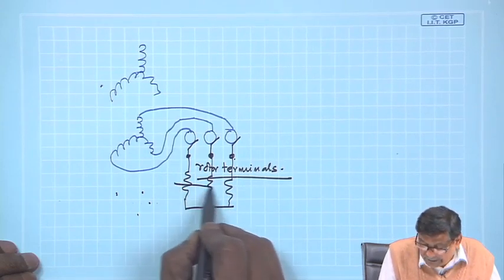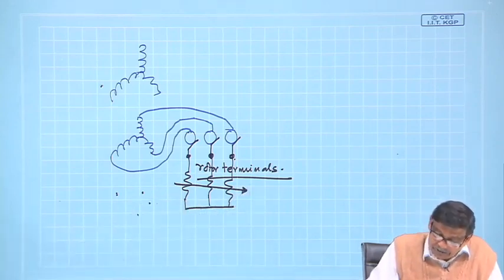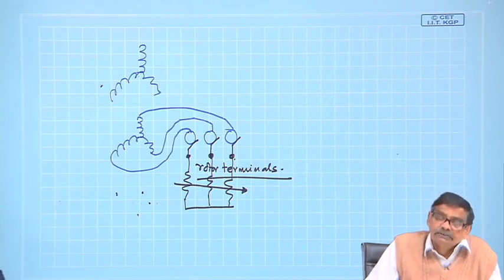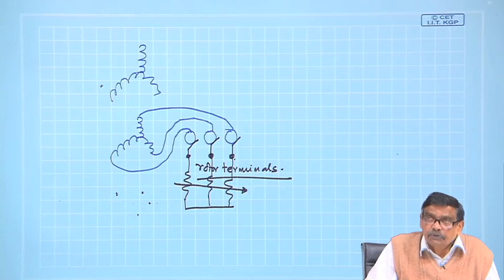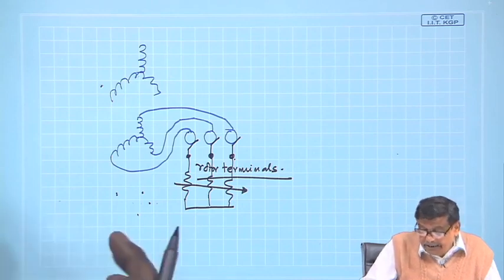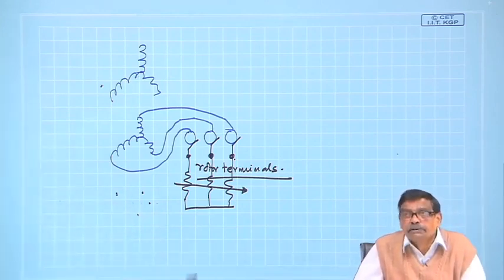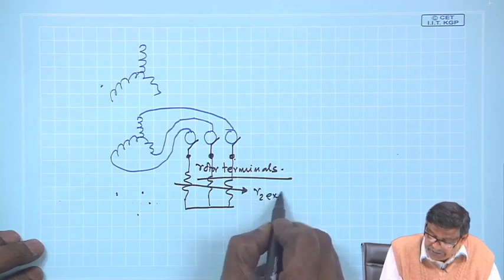This is one of the very nice points about the slip ring induction motor, that you can vary the starting torque, and you can even make the T max, which the motor is capable of developing at some slip, appear at s equal to 1 by appropriately connecting external resistance.